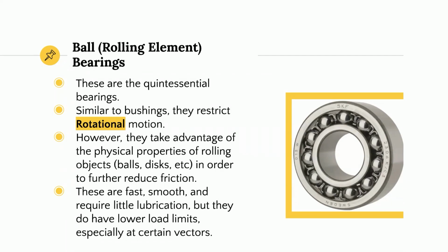So for example, you don't want to have angled forces going on a bearing, or you might not want to press it directly into that center diameter area of the bearing. It's going to break it.